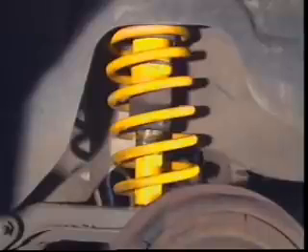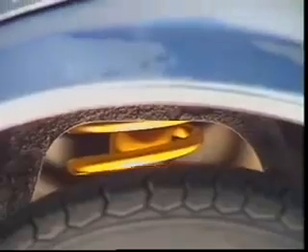To reduce these effects, a manually adjustable air spring can be incorporated into each rear shock absorber. The air spring consists of a flexible rubber cylinder which seals the outside of the upper and lower halves of the shock absorber. The shock absorber is a standard hydraulic type, providing normal dampening action.